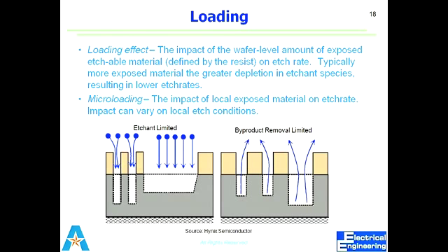Okay, so I told you that the loading effect is one of the parameters that you also need to take into account. We did not talk about the loading effect at that time because I knew that in the next slide we'd be talking about it. So what is the loading effect? While etching, due to the loading effect, the etch rate actually changes. Generally, say I have BHF and the etch rate is 250 angstrom per minute maybe. If it's 250 angstrom, and instead of one wafer I have 7 wafers loaded in one boat and put all together in the same etchant, then the number of etchants available for the exposed surface area actually decreases. So this is what we call the loading effect.